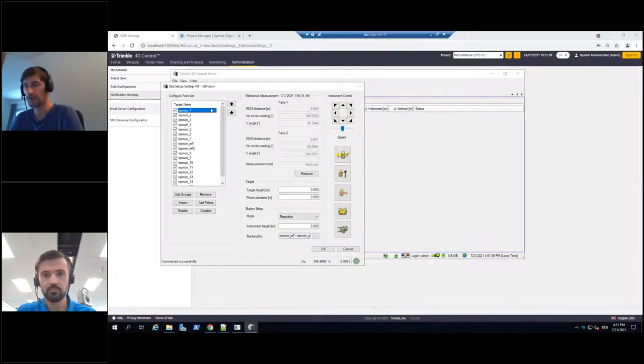This is really helpful information because it helps to assess displacements, in particular if the reference date differs from target to target, as I said. We also added the information on the measurement mode. Like here it's auto log because the distance is below 20 meters, but if I scroll down, I'm sure we will see fine log. Yes, here 37 meters, and then it shows fine log, for example.